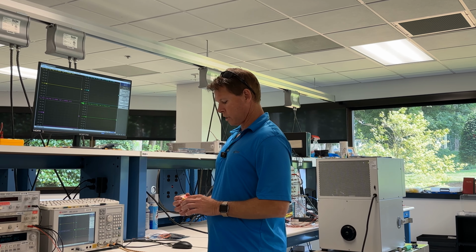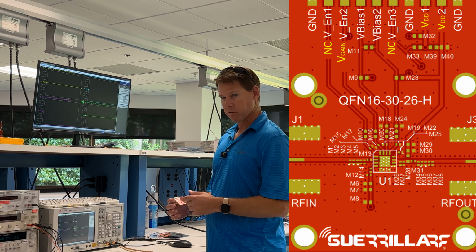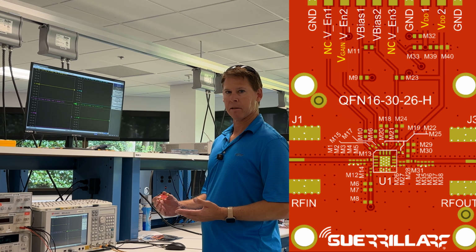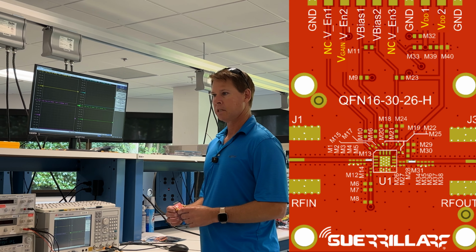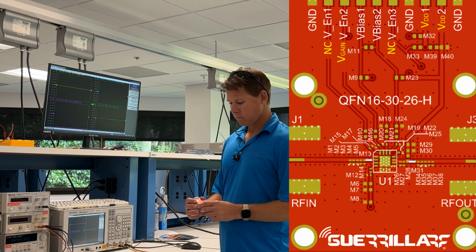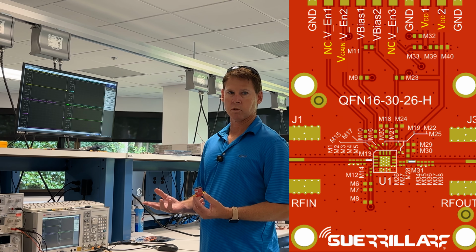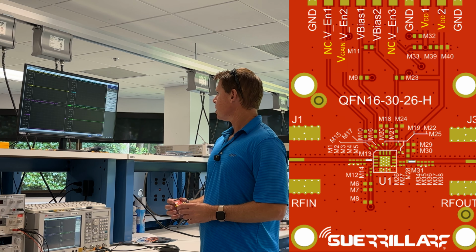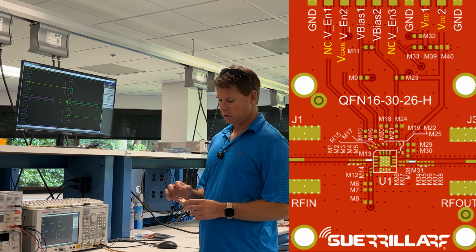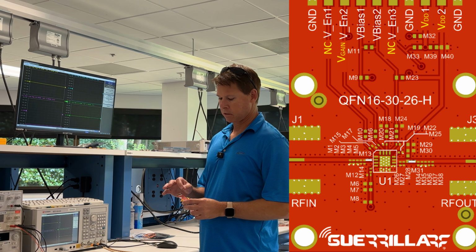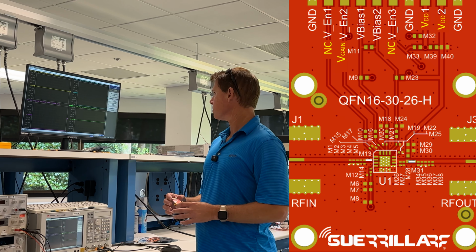You would have to remove the DUT and remove all the components that you would have in the matching, and basically just put 0 ohm jumpers or some kind of jumper to get all the way to where the part was. And so you can measure an open, which means the part is off and it's just into an open circuit.